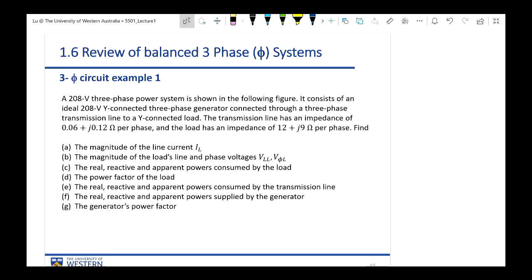If you say 208, of course, we want the user to get 208 volts. If I'm the provider of the electricity, I give you 208 volts. But after transmission, this voltage can decay. So at the receiver side, at the user side, the voltage may drop to 100 volts. That makes sense. So all the voltages I give here are user side voltages.